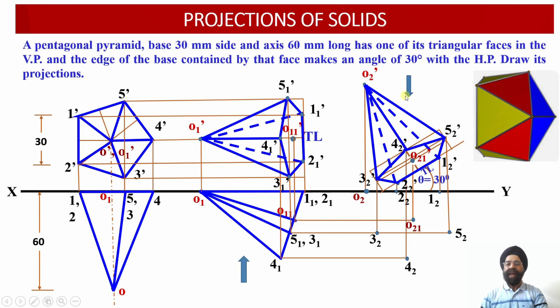Now please check, as the observer is going to look at the solid from the top, the farthest point is 2, 2 dash. So anything joining 2, 2 in the top view projection, that is anything joining 2, 2 point in the top view, should be drawn dotted unless it is constituting the boundary of the solid. So let us join the different points.